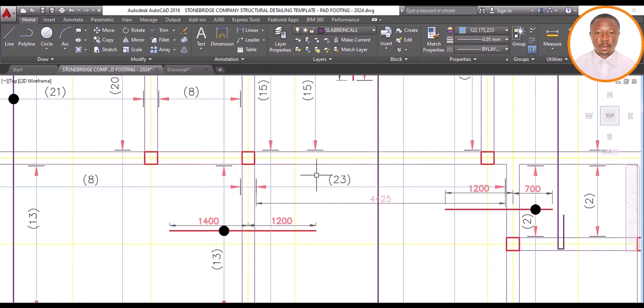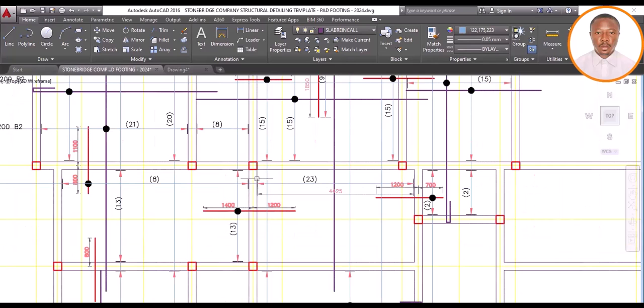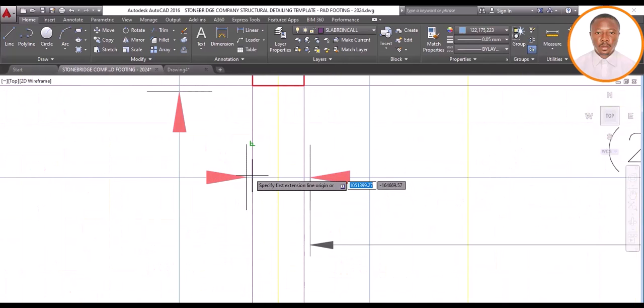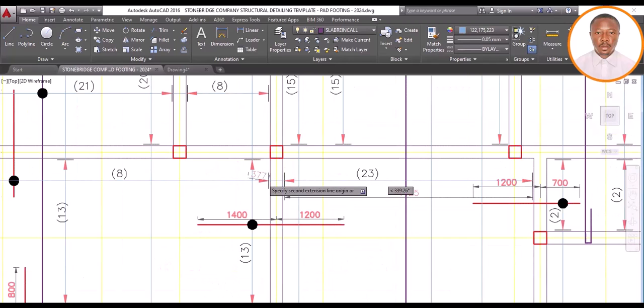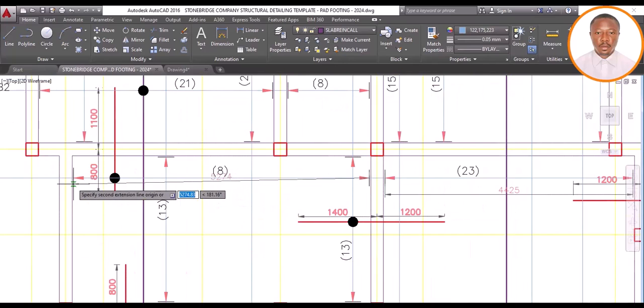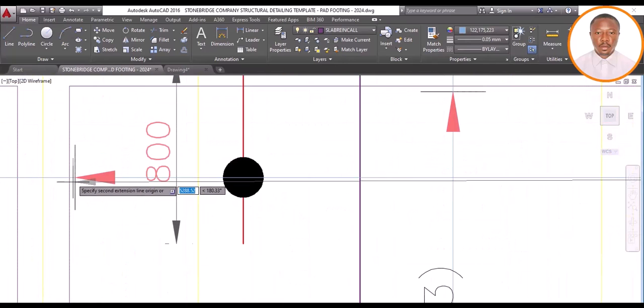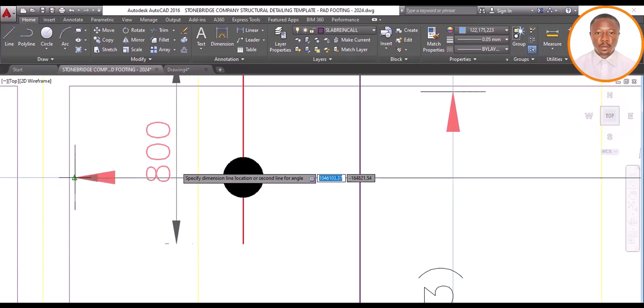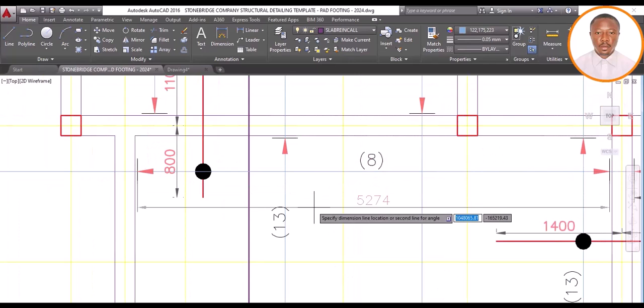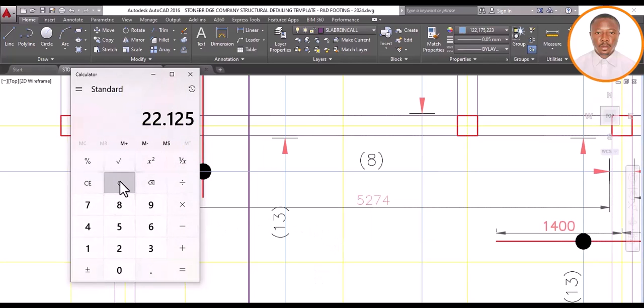We're done with this. So I also come here and take my dimension and see what we have for us to calculate. Let's do from this particular point, so we move to this point here. Now it's very important that you take your dimension and divide by 200. That's our base spacing, because from our structure, that's what we got. So that's why we are using 200.